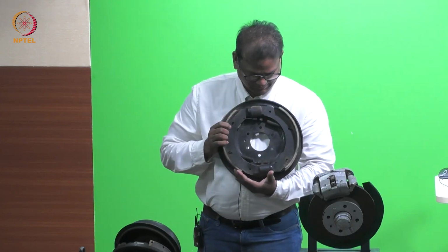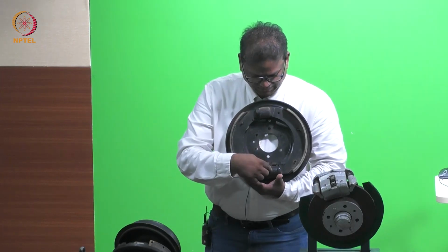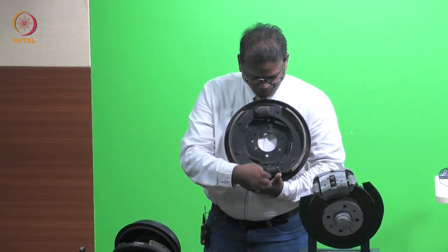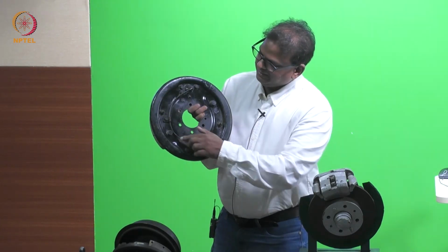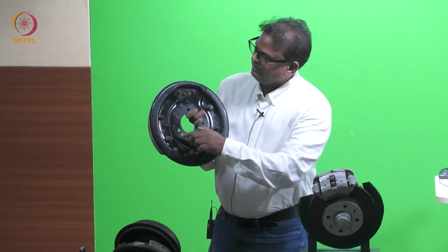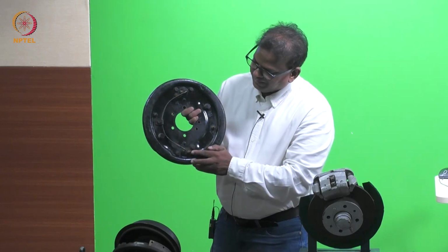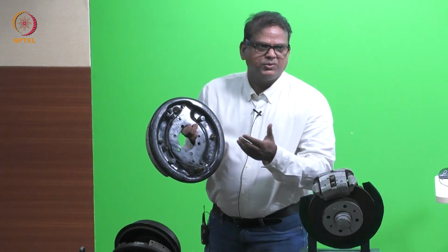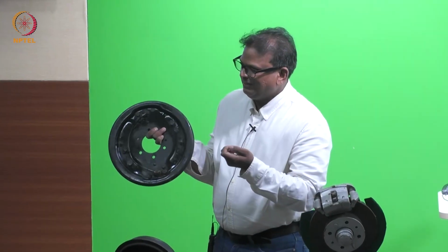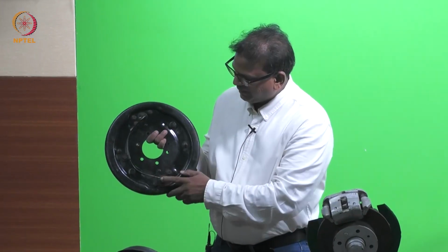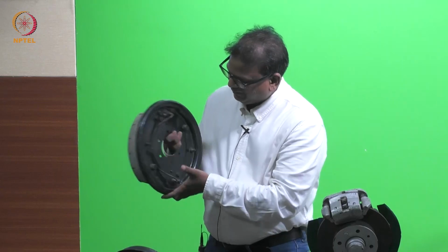You can see that, and this will have a piston again inside. The fluid will go through. You can see how the fluid goes inside, right? And this is for bleeding. Bleeding means suppose the brake fluid traps air, you have to release the air, otherwise you will have a problem. So that can be eliminated using this bleeding thing.